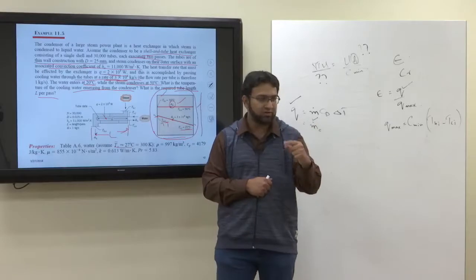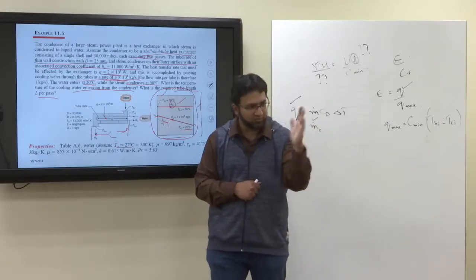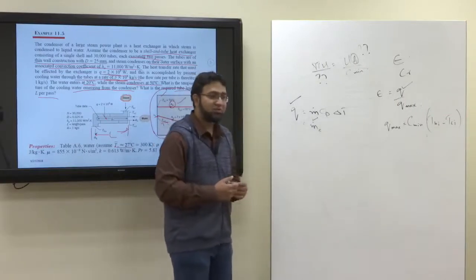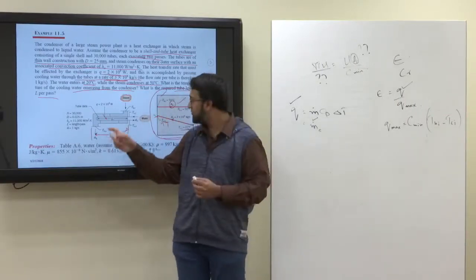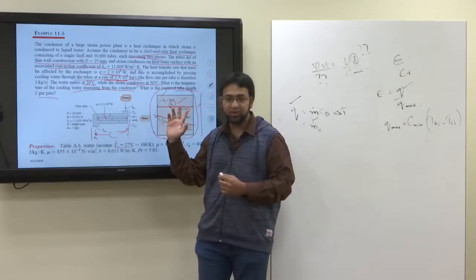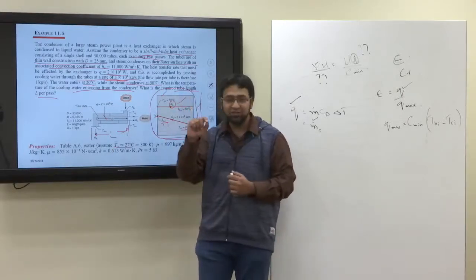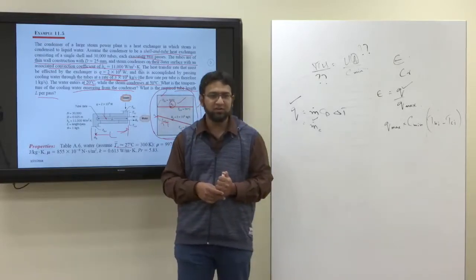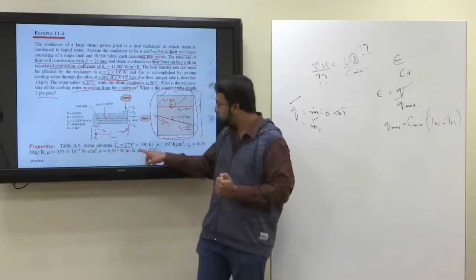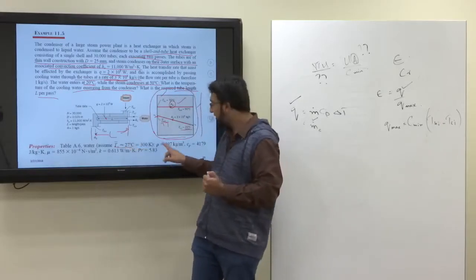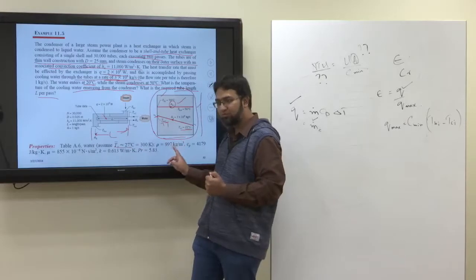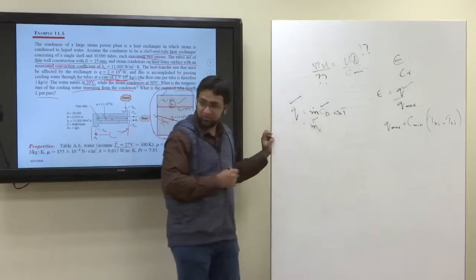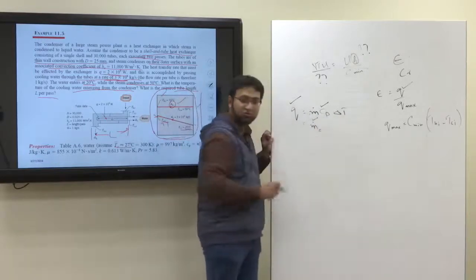The problem needs to be resolved again, although you will not be solving it again. You will be solving it one time. Okay? Because you see, suppose you take TC out as 49, then your T average will be how much? 20 to 49, 20 plus 50 is 70, approximately 35. So you will use 35 degrees here to find the properties of water, and then you substitute the Cp value at 35 degrees, and you will get TC out from here.